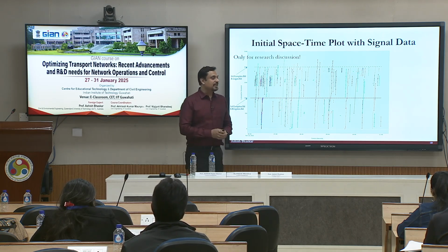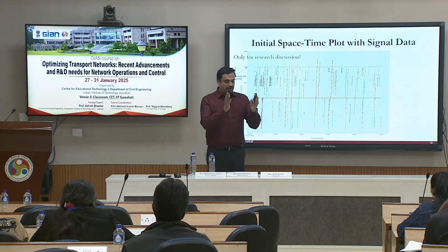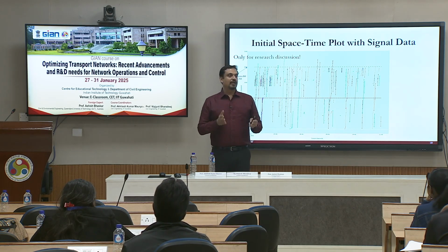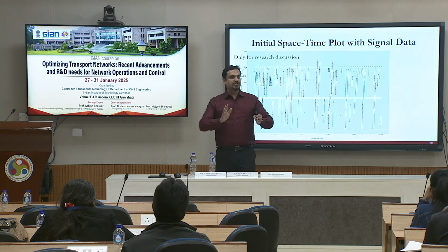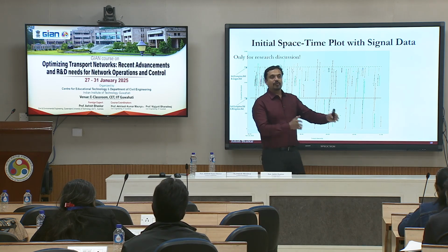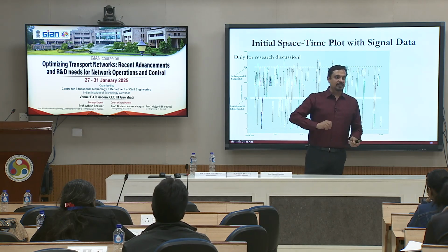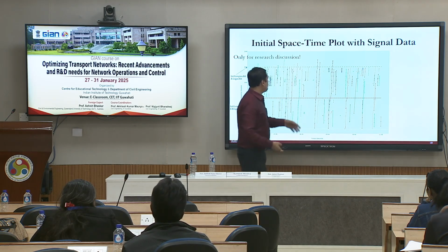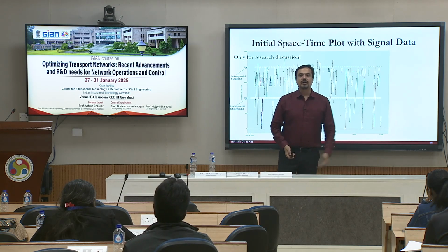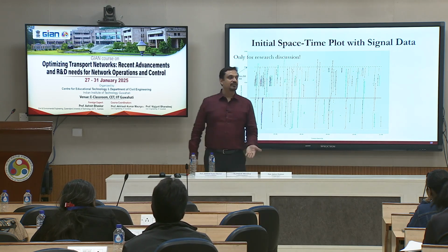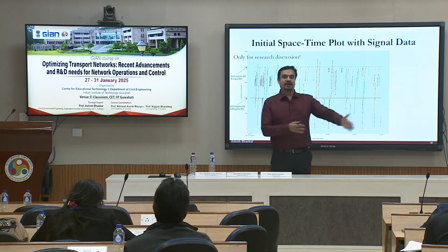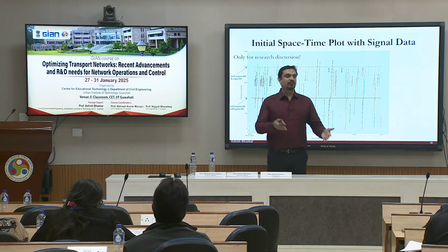In this case, what you do is you study that time interval for a large number of periods. So let's say from 11 to 12, I've made a change in my signal timing. So this is the time of interest to me. I am observing data for multiple days beforehand. I get my trajectories, they are randomly selected trajectories. Some of them may not be stopping, some of them may be stopping. So if you go for the last time interval before, you can figure out what proportion of those trajectories were having a split failure. Because you have randomly selected them, you can show the likelihood of a split failure on that approach.